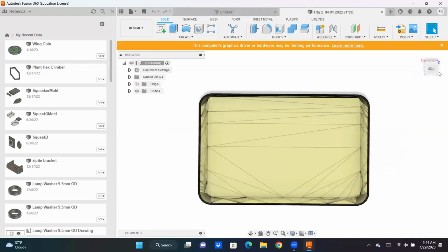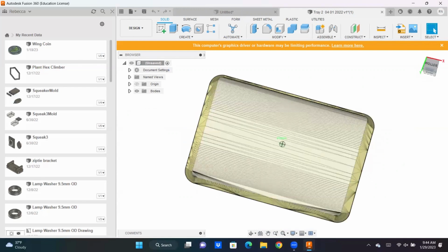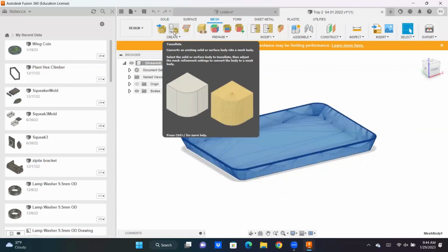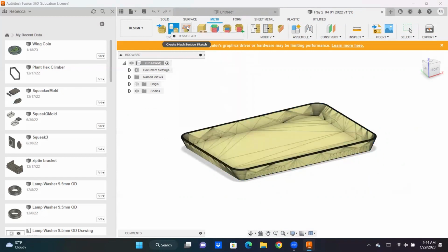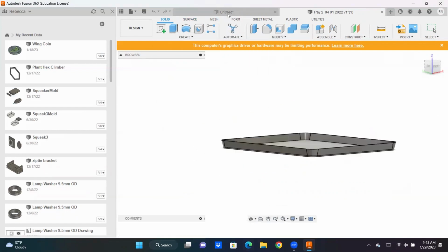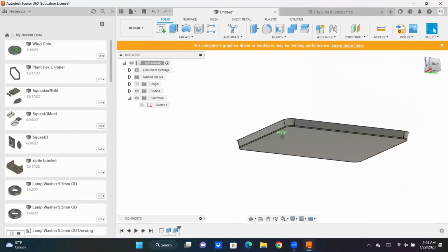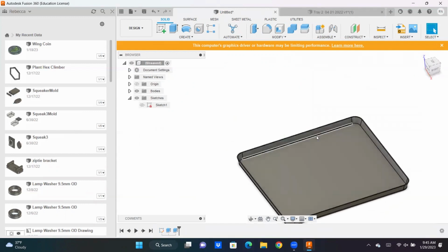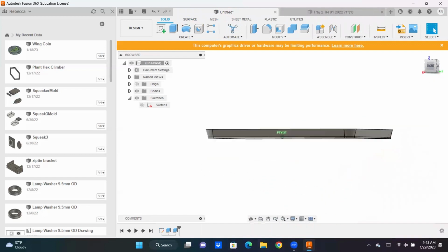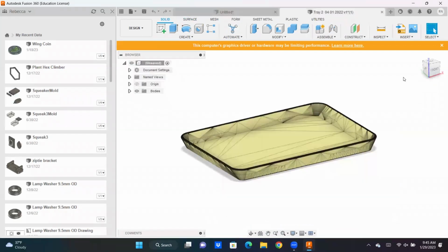One last thing I wanted to look at with our mesh object here is if you look, you can see all of these little gray lines in it, and those are all different. Each enclosed shape, each enclosed area is a face or a surface, meaning that this mesh version has a lot more geometry than ours does. You can see ours has a bottom plate, the walls, and the corners. For 3D printing, the simpler the better.